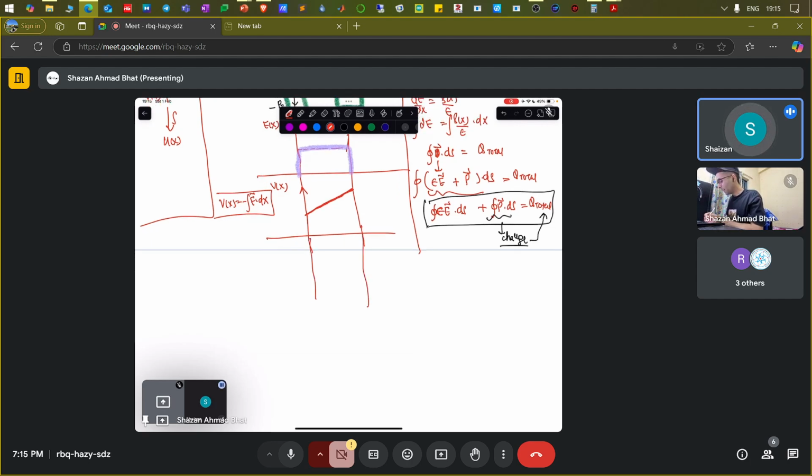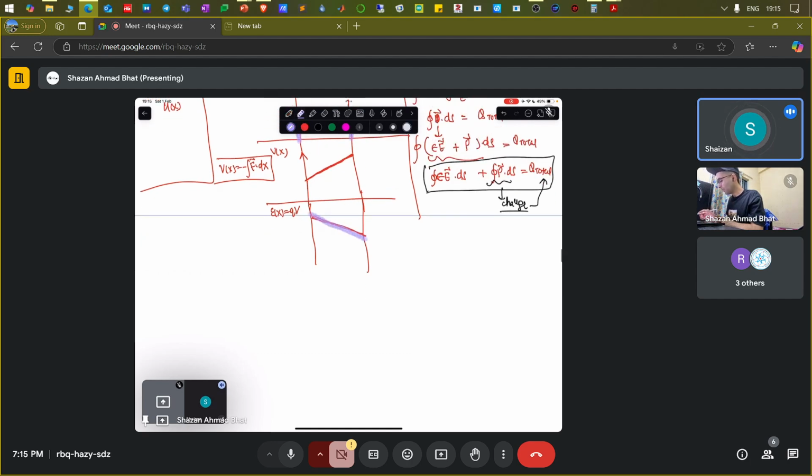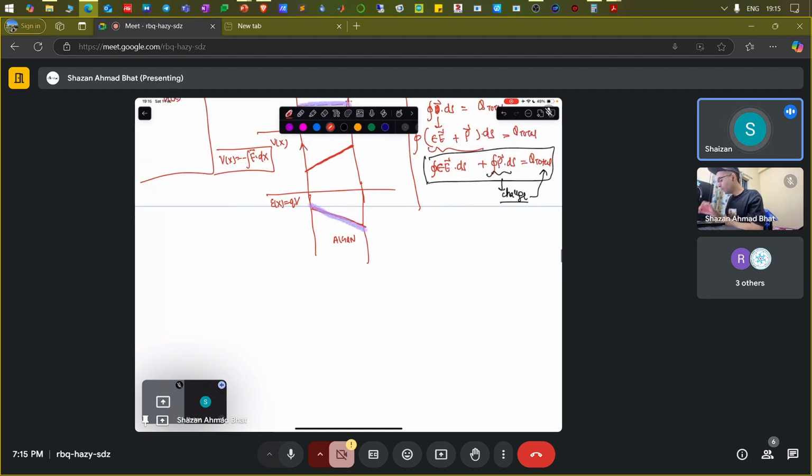And if you invert it, you write the energy, which is minus q times potential. You get something like this. You have to invert it. So this is the exact band of the aluminum gallium nitride, AlGaN, structure. That's why you see that it's a downhill. Any electron here will go down the hill and settle at this particular position. So this particular thing is the band of this.